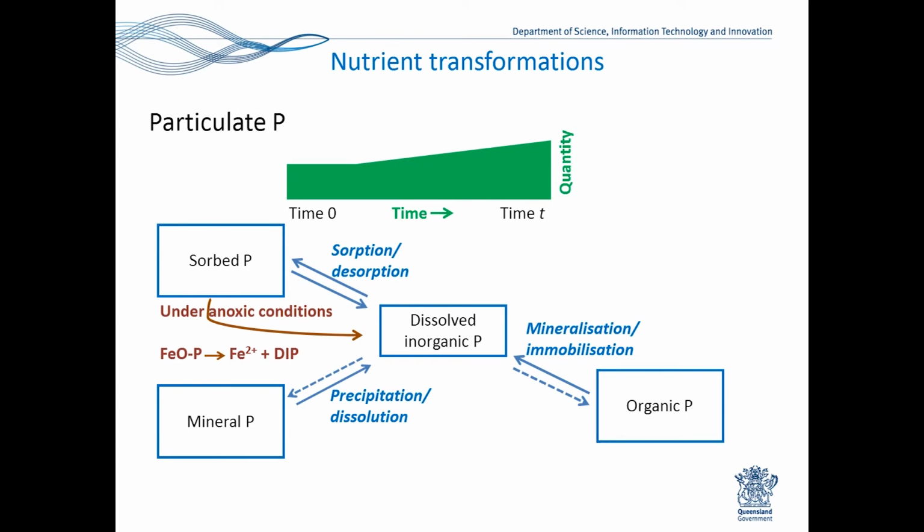That occurs over weeks or years in the agricultural context, but in terms of soil P on a soil particle or a sediment particle getting into a water column and going through wetlands, once these conditions occur, those chemistry reactions are very, very fast. We have the situation with the phosphorus attached to a sediment, moving through a wetlands or moving through a water column out to the reef. It's those basic chemical properties, absorption properties of the sediment which determine the bioavailability of that phosphorus. If that phosphorus can be easily released, then it becomes bioavailable. If that phosphorus is tightly held by the sediment particle, then in terms of biology, it's not an event.